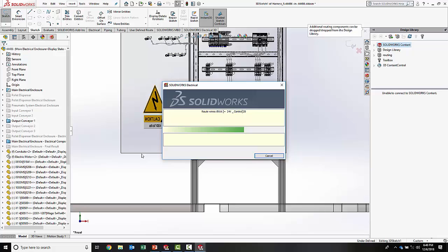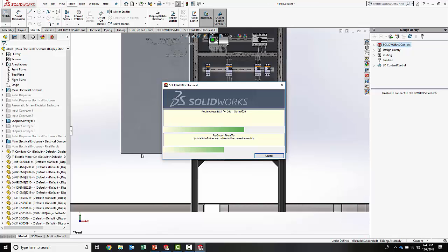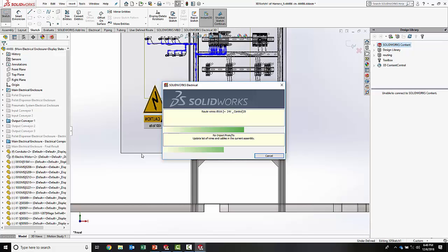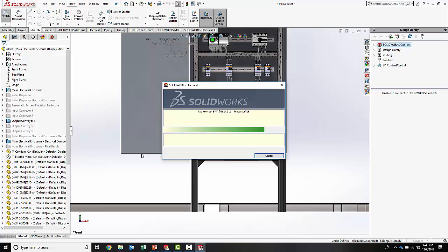You'll see the yellow dashed lines. Those are what you would get if you were doing SolidWorks Premium routing, because it's going shortest point to shortest point. And then saying, oh wait a minute, I've got to follow a path. And then it follows the path. These ducts, each one of these ducts, has a routing path in the middle of it, so it knows that it needs to route that harness or that wire along that. And it can calculate fill ratios.